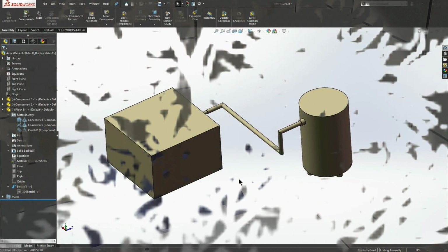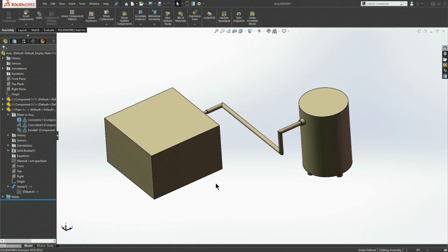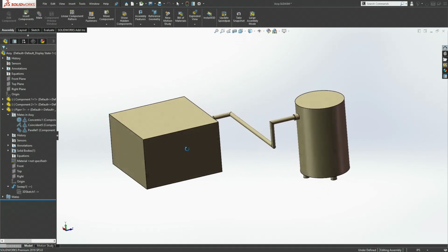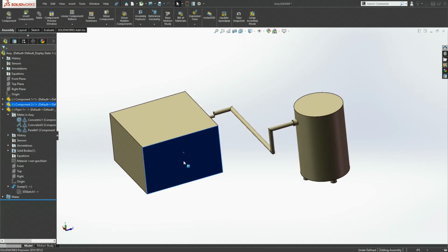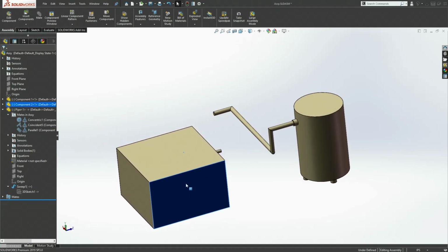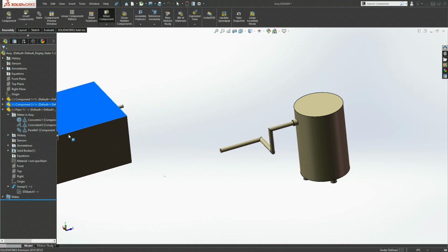I haven't done a SolidWorks video in a long while, and I would sure like to do at least one more in the near future. So here I have an assembly, and let's say that this is a sample plant with machinery that's piped together, and let's say I need to make a change. Well, normally I would have to redefine this pipe, but if we edit things in context in the correct manner, I simply hit rebuild and the pipe will update itself.